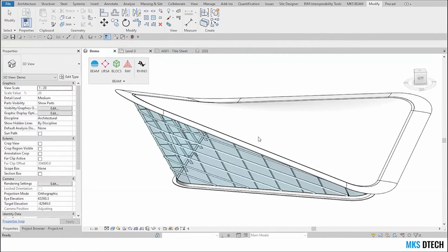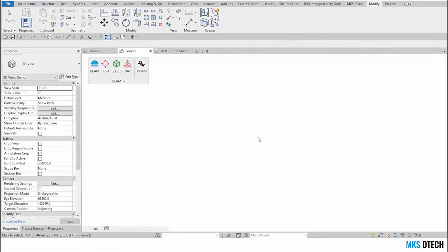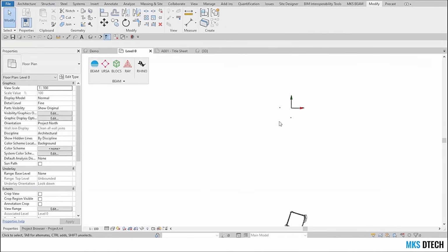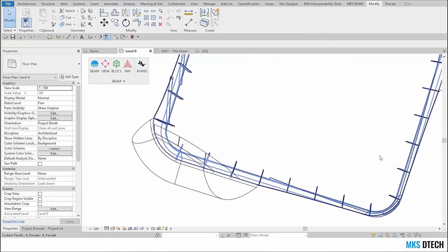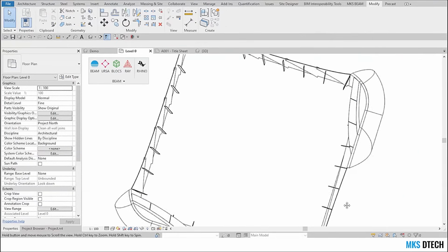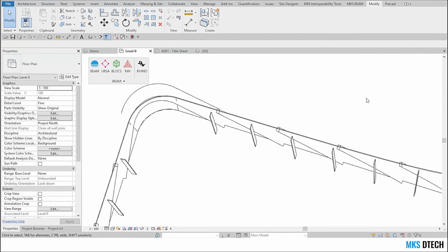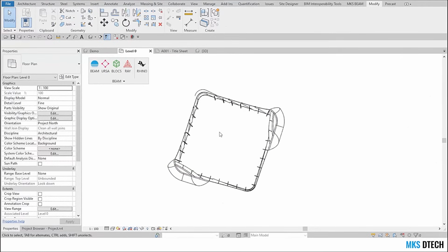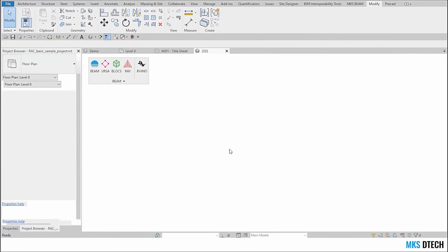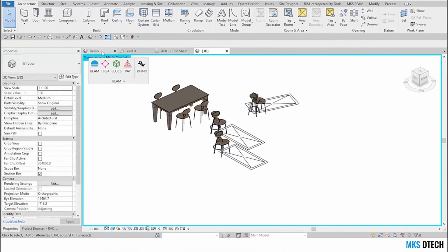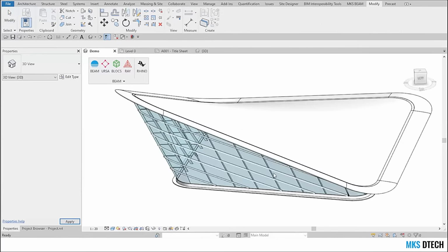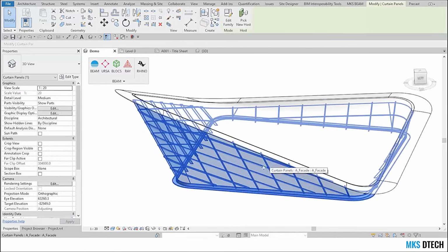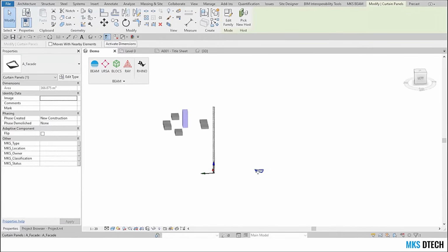Yeah, Mauro? So Mikael, I think it would be good to mention the difference between importing a family as loose geometry and as a block in terms of positioning of the geometry, because in this case, when you are rotating the object, it's slightly more distant from the origin. And I think it would be really nice for them to understand that that's why blocks are super convenient for the placement. I think this can be nice.